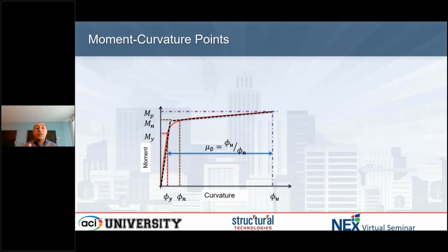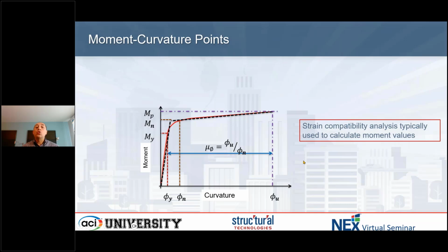Now that same cross section, if I'm looking at the moment curvature, things we've done in school when we're studying concrete and doing analysis, I can determine what is that ultimate condition with the ultimate strain, what is that curvature and that of yielding, and I can calculate from that what is the rotation, right? By taking that change in the angle times the height times the plastic hinge length, I get the total rotation that I could achieve at the plastic hinge.